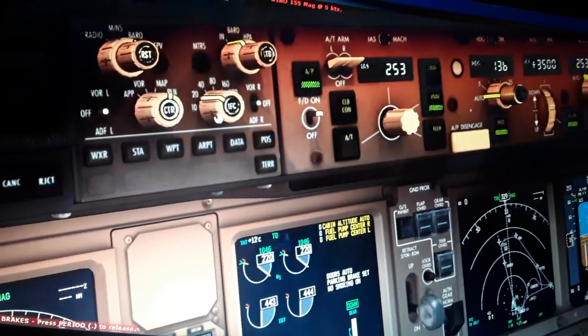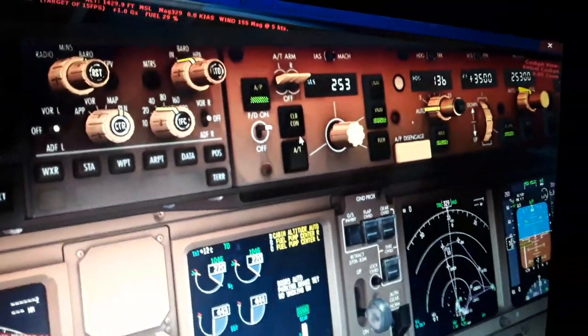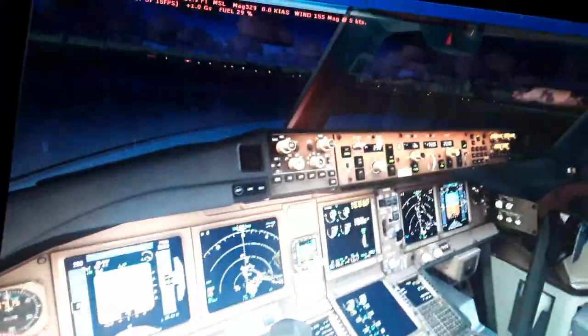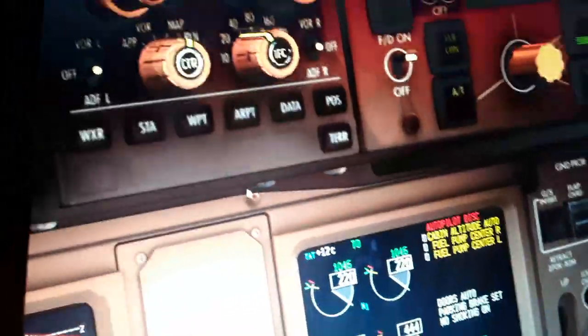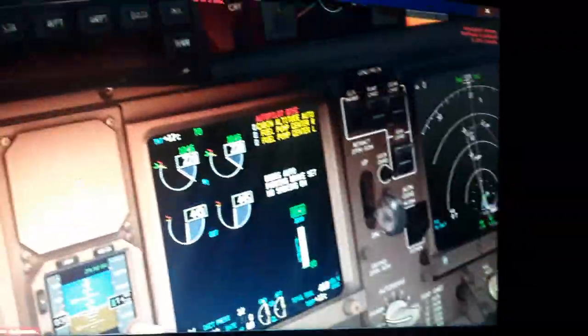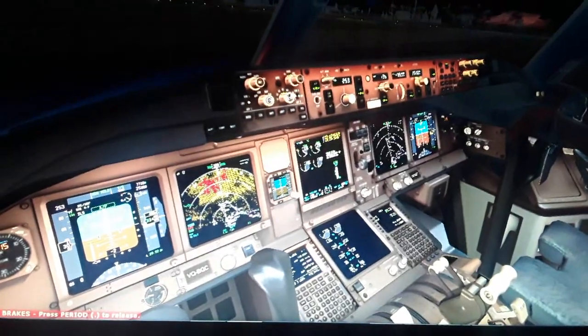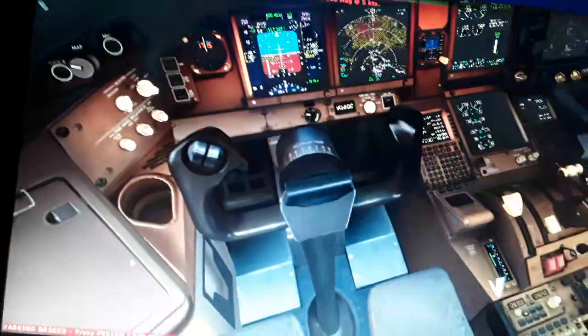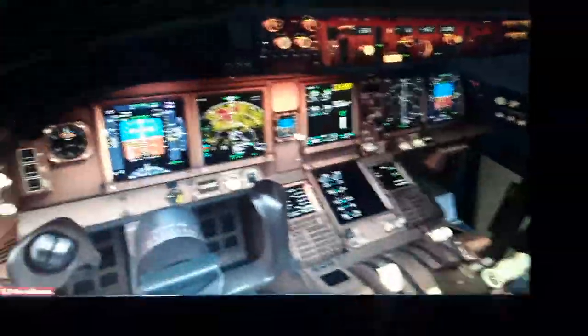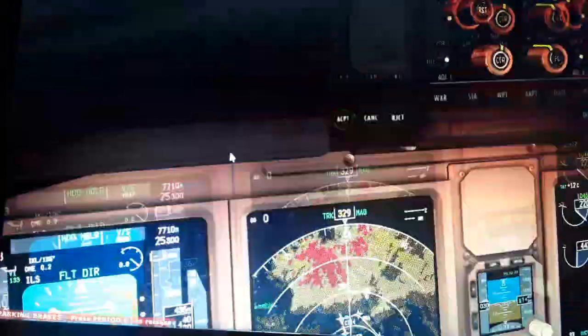So we're gonna use again this, the autopilot disengage, engage it again. So we're gonna disengage the autopilot using this switch here, the autopilot disconnect switch. So we have the warning again and the warning here, autopilot disconnected. We press one more time, engage, press it one more time, disconnect, and confirm the disconnect action. Second disconnect, confirm. So I'm gonna show you the rest now of the systems.